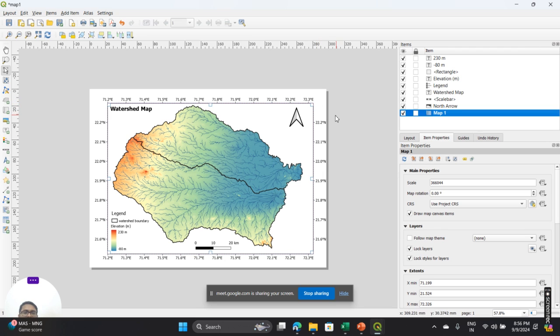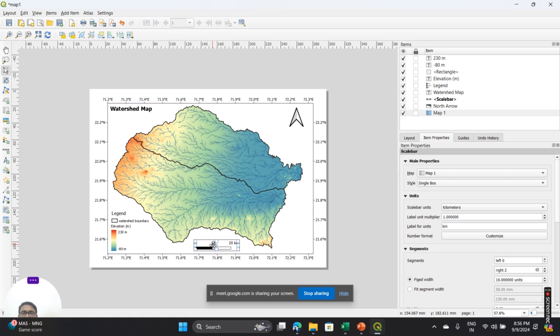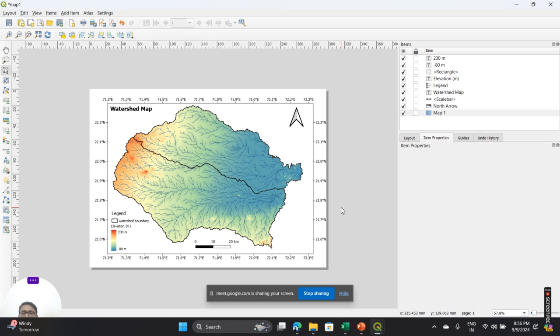and then go down and click on draw coordinates. Under draw coordinates, you select the degree, decimal degree with suffix. So it will add this north and east. And you can change the coordinates precision from 3 to 1. Like this, your entire map will be there. If something is not looking good, you can change it to some more places.